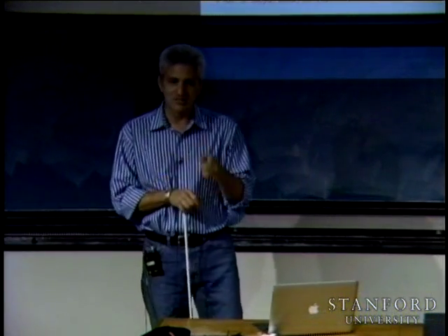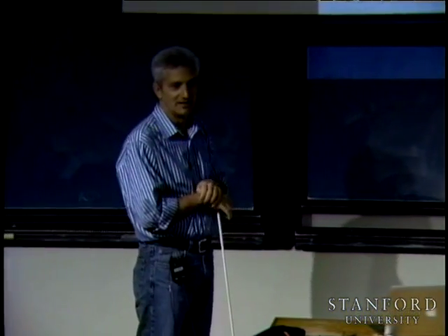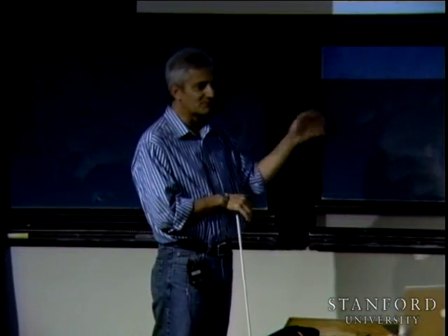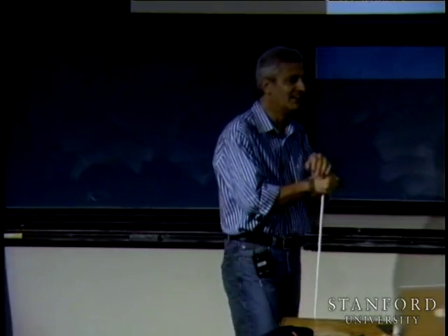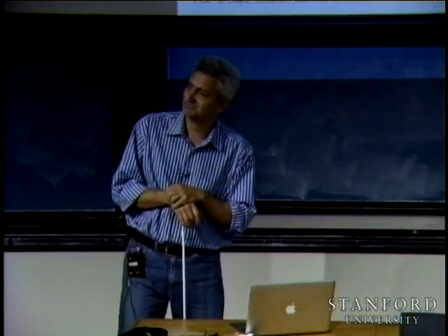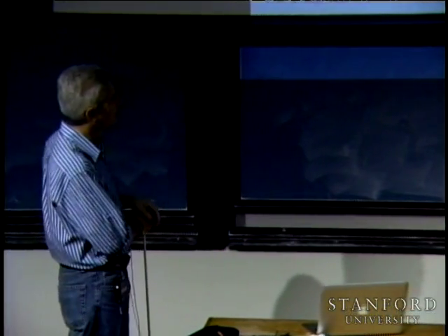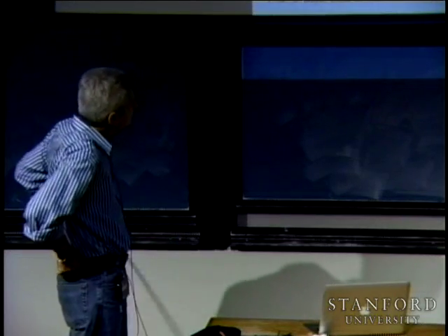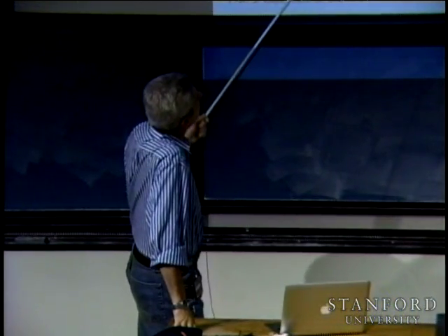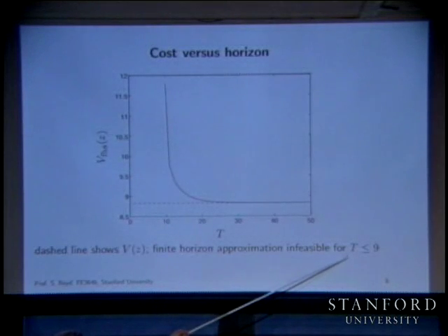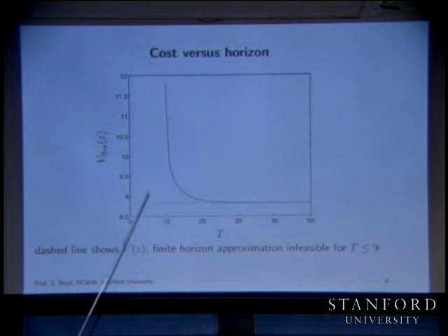Okay, so this is, in my opinion, the real theory of control. This is the first theory that's actually useful. Versus the business with B, AB, A squared B, and all that, the Krylov subspace, as we now know it, being full rank and everything. It's classical, and as far as I know, it doesn't really have any actual use. But okay, so here's a real controllability analysis. It tells you, can you hit the origin? And it says that even in 9 steps, you can't do it. It's infeasible, so the cost is plus infinity.